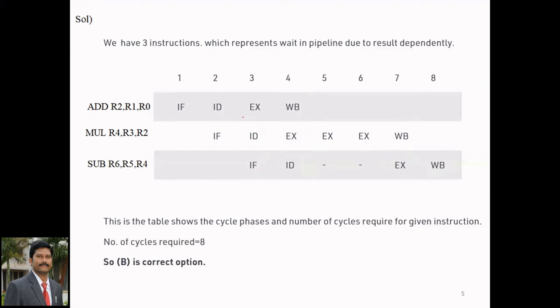Let me tell you the conclusion. So actually, the operand forwarding technique: here, after completing this, R2 is available at the 5th clock cycle, then execution should start here, EX, EX and EX. But because of the operand forwarding, when it is writing, there is also a path to the execution unit, so it can start here only, EX, EX and EX. That is the operand forwarding technique.